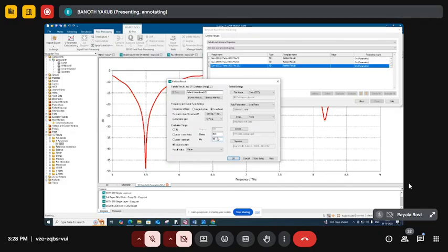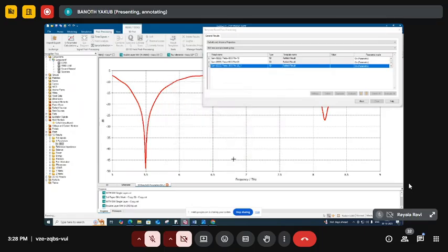At theta angle of 90 degrees, you can change the phase from 10 to 150 degrees. You can see whether the axial ratio plots are matching, that is, whether our particular antenna design is matched or not, at these phase angle variations. So phase 30 degrees you can change here. Then select it, and the phase angle is changed to 30 degrees.